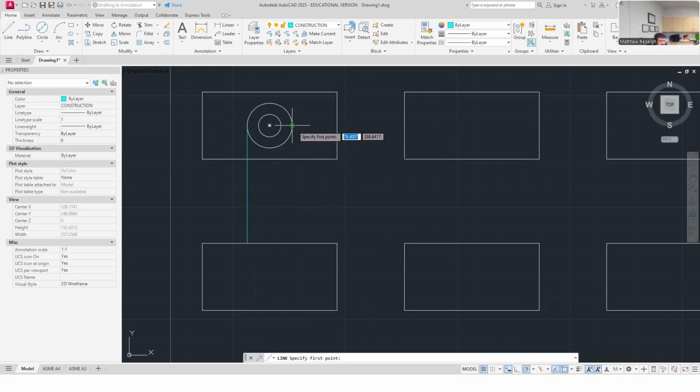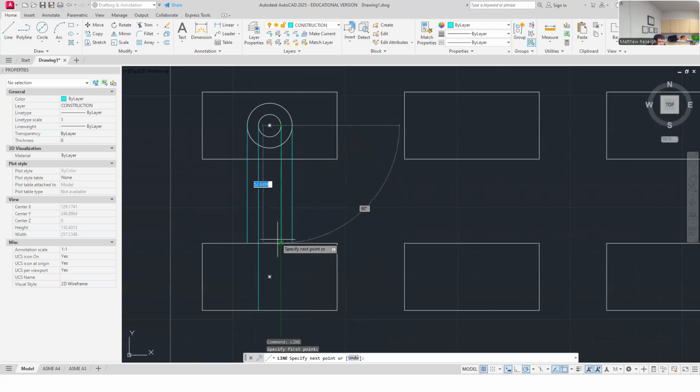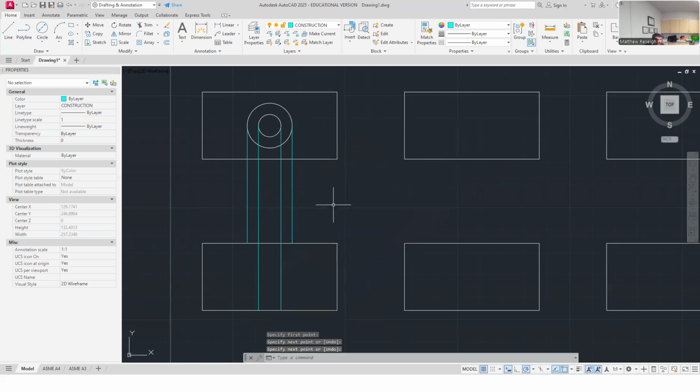And let's do this down to the next one. So I'm going to pull the outermost sides of that circle down, and then I'm going to pull the innermost quadrants down here like this. And technically, you could draw some of these fully down, and I'm just kind of being strategic here, knowing what I'm doing, but I'm pulling these inner ones down further. That's the inner bore of this counterbore.